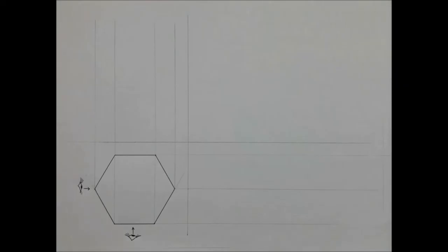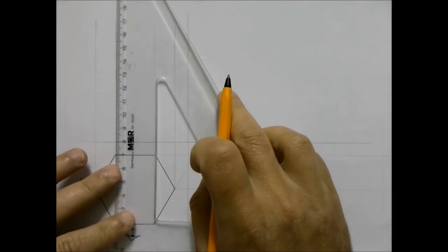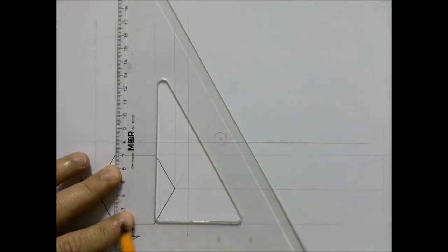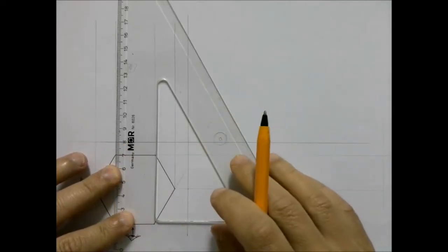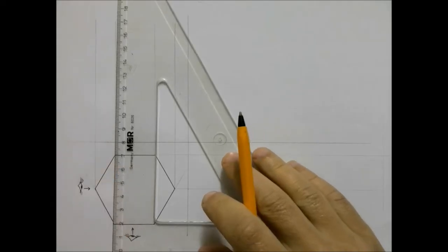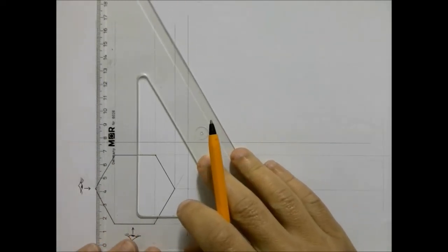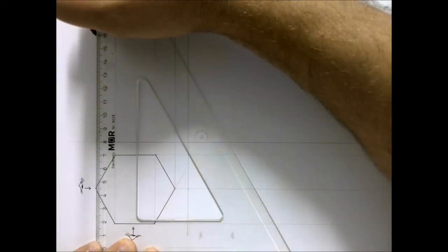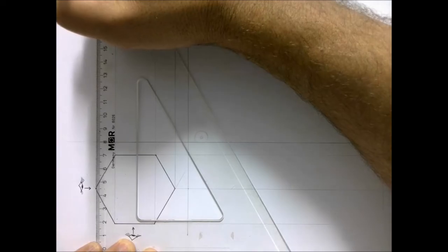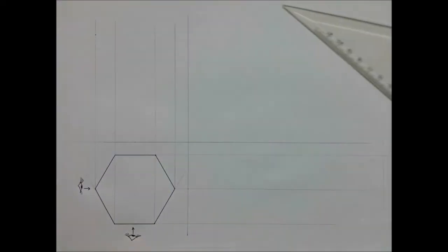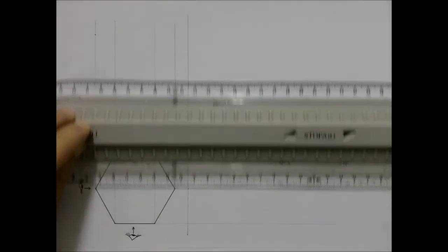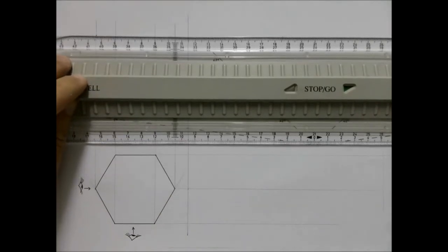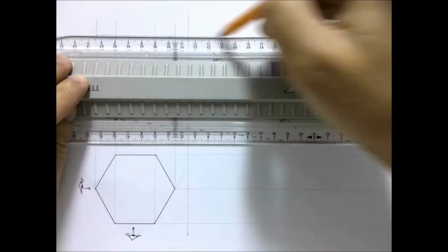Okay, if the instruction is for your front view to be 10 millimeters above the axes, you can go ahead and just go and put it in over there. But for the purpose of this video, I'm going to just go and make it on the actual axis, and I'm going to make it about 80 millimeters high. Okay, so there's my 80 millimeter mark. In this case over here, I'm going to make it a pyramid. So I'm going to project that bit of information right across.